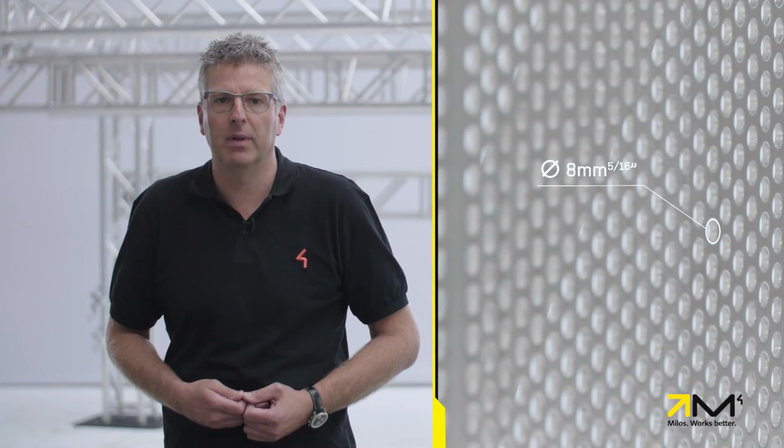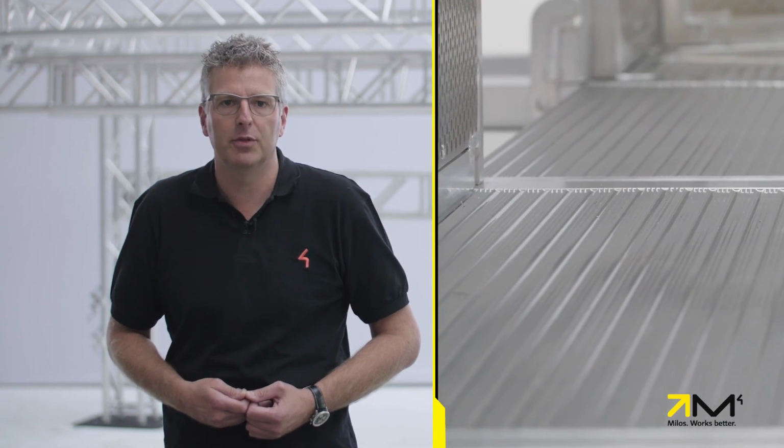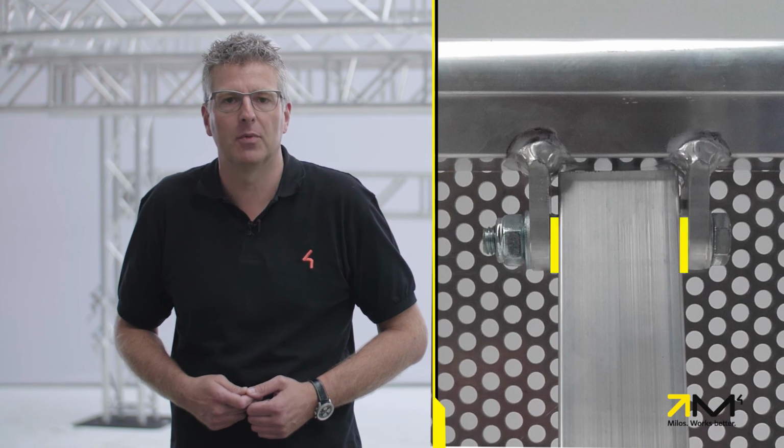For safety reasons, all aluminium profiles have rounded edges, the holes in the perforated front plate are too small to jam fingers, the front edge slopes down, and the floor plate allows sit-down of the audience. It might sound weird, but we even thought about the sound guys when we developed our barriers. Therefore, all moving joints have plastic washers to make them rattle-free.